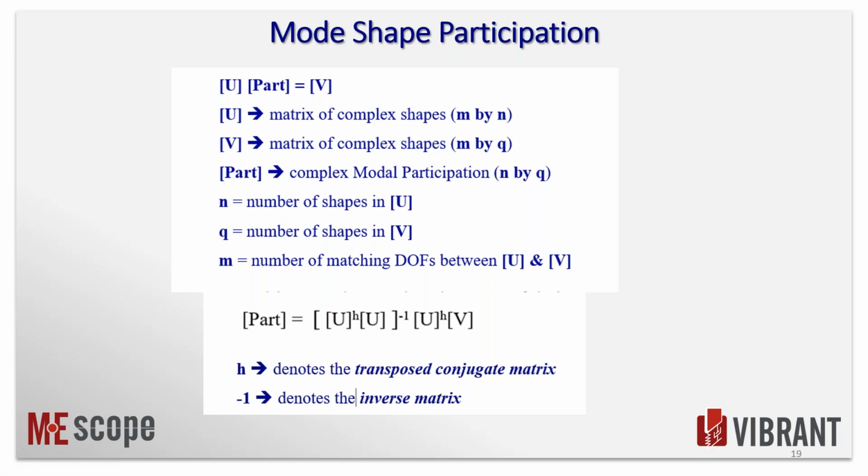Again, normal modes are just real and imaginary, so they're not complex. A normal mode that we get out of an FEA. But in the real world where we have damping, the OMA mode shapes have damping. We saw that when we curve fit the data.